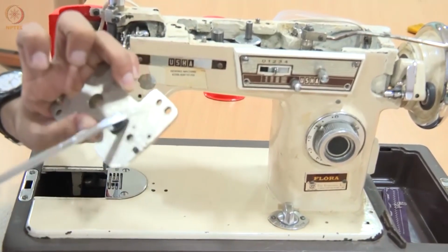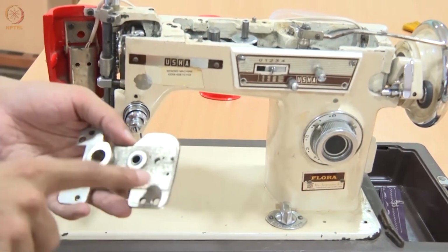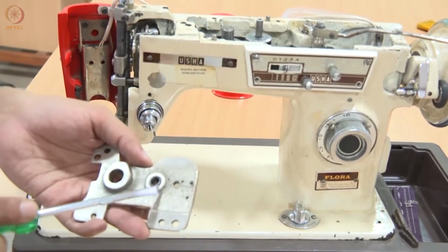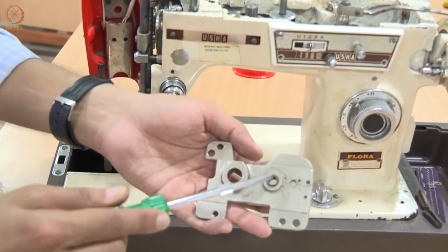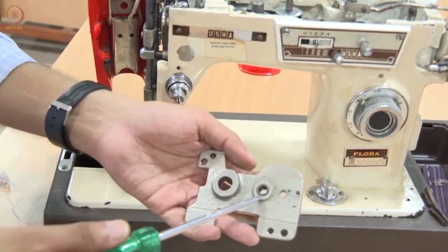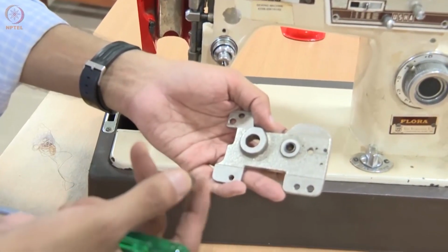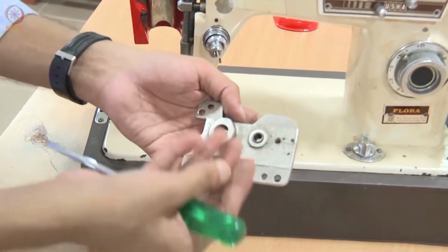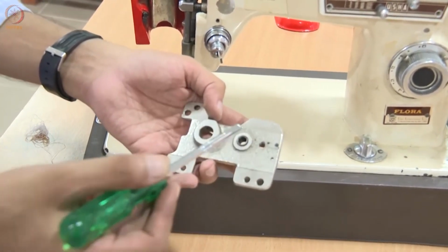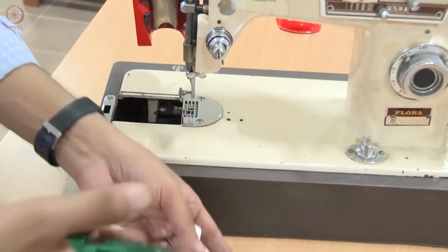This is a metal insert because typically you don't want to use the same material. This bushing is made of an alloy. It's a softer metal. You have materials like lead. You have a different, softer composition, such that it provides lubrication also to the bearing.